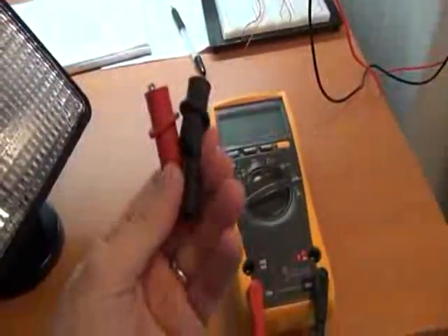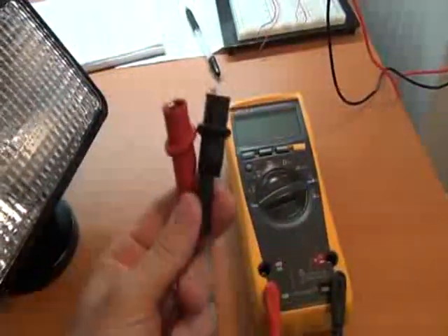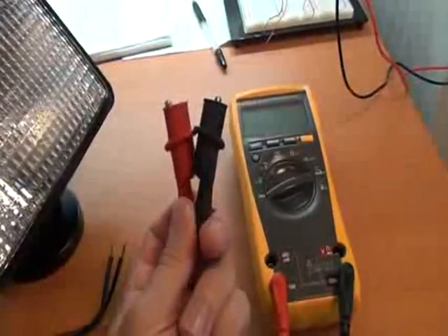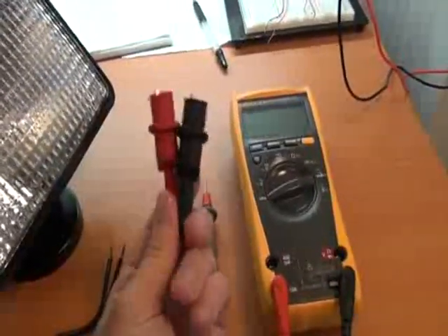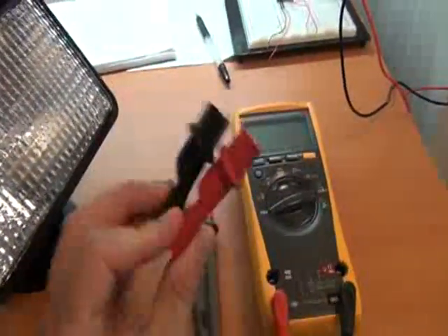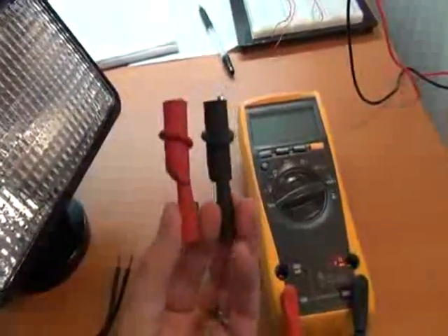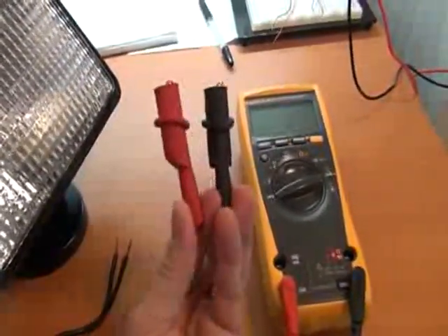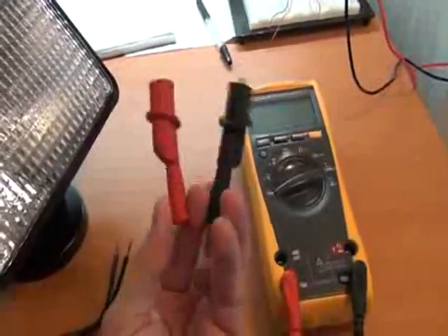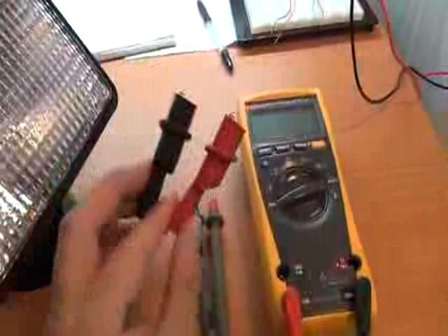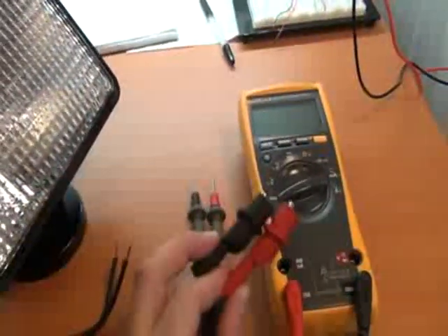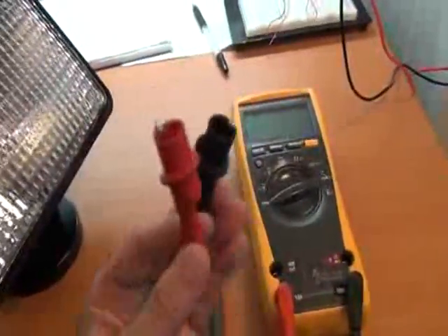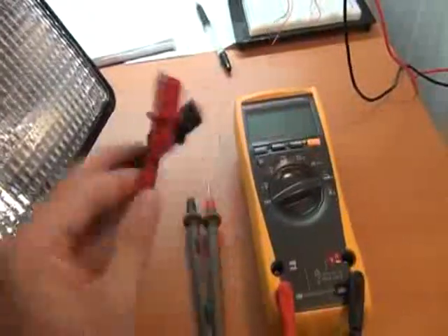Now, someone made a very fair comment in the previous video. If you remember, I used those little crocodile clips to connect to that LED when I was measuring the voltage across it, and they said there could be some safety issues with that. Now, they were dead right. In that application, when measuring voltage, you can get away with using crocodile clips and thinner wire, but at the end of the day it's good practice to always try and be safe. The safer thing to do is to get crocodile clips that attach directly to your probes, like the ones I have here, because they can handle more current. But I'll demonstrate that now.